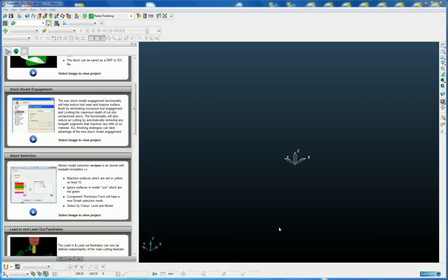This means that if we use the same colour convention and model naming convention and level naming convention on all our parts, when we read in a new part, the toolpath template will automatically set up the component thicknesses used in the Smart Selection. Let's open an example project and have a look how we use Smart Selection.